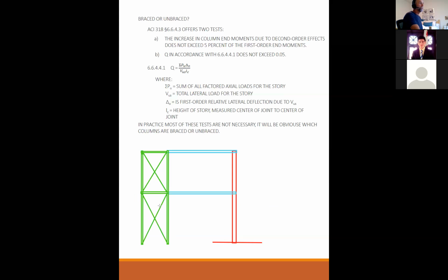That's the lateral system. And this is the column that we're not sure is braced or not braced. If this was a shear wall, this is braced. If this was a moment frame made out of concrete, this is braced. But if this is a rinky-dink two steel brace frame with 1/2 inch or 3/4 inch steel rods as X bracing, this may not be braced.